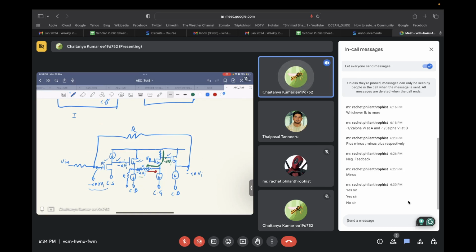In the DC operating point, you will have the list of parameters. Let's say it will have GM, GDS, VDS, VDSat, all these things. You can take GM and do a temperature sweep. First of all, do the temperature sweep and plot GM with respect to temperature. If you see that it's constant, or basically, it won't be exactly constant, it will be constant with respect to what you would have got if you would have put a fixed current inside that GM.